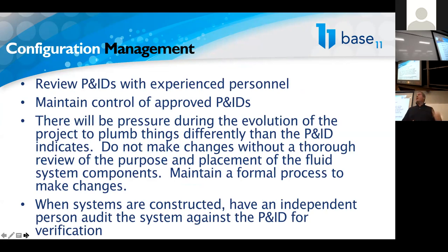It's very, very important and critical to identify before you try to operate the system. Generally speaking, we found those during leak checks. It hasn't gotten to the point of when we actually try to attempt flowing propellants, but it's happened. And so having a third party that's not a part of the system in the first place, or not their primary role, do an audit is extremely valuable and helpful.